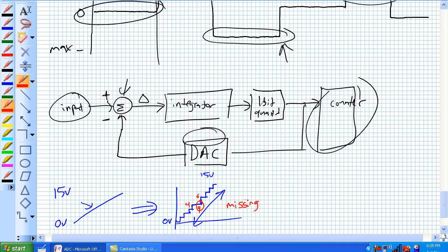The other thing that's common in analog to digital conversion errors, let's say you have this 4-bit converter and you're putting in an analog ramp, and you go 0, 0, when you should be going to 0, 1. Something's wrong there.